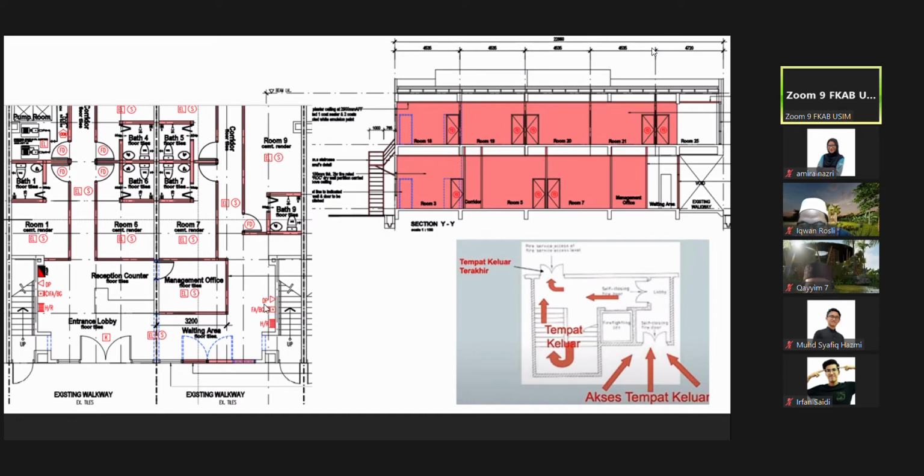Okay, so look at the plan here. I can foresee that if the story is only 2-story here, you can design another fire staircase, meaning that if the story exceeds 12 meters, 12.1 meters, you have to refer this to bylaw 133.